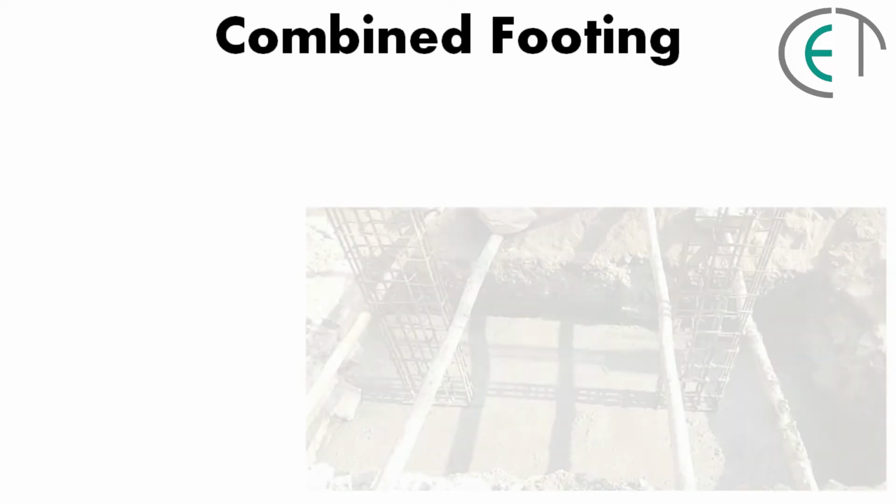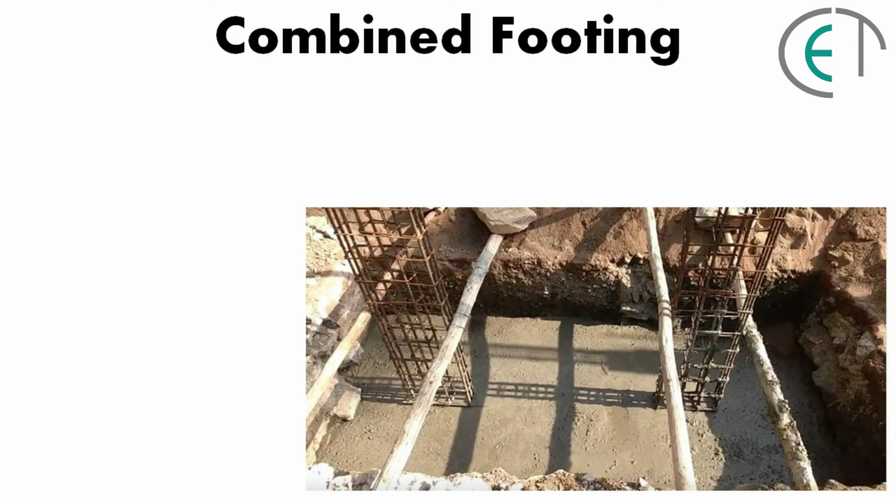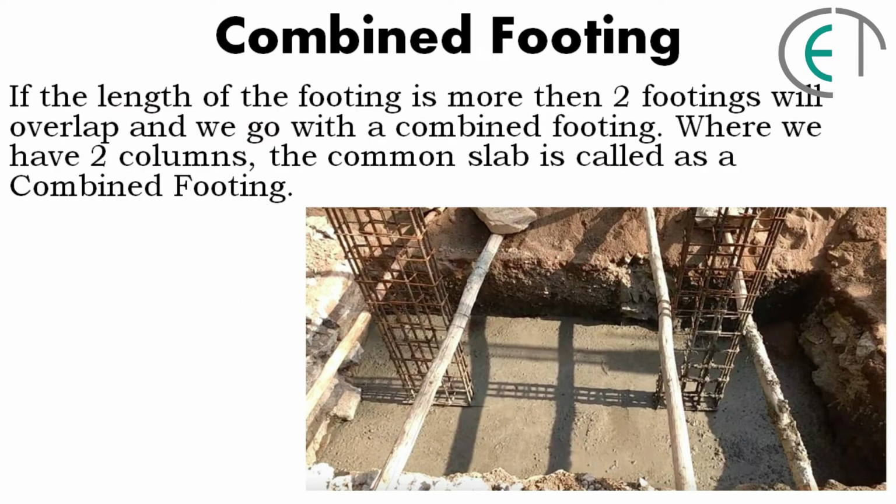In the previous video we discussed isolated or spread footing, and now in this video we are going to discuss combined footing. If the length of the footing is more, then two footings will overlap and we go with a combined footing. Where we have two columns, the common slab is called a combined footing.